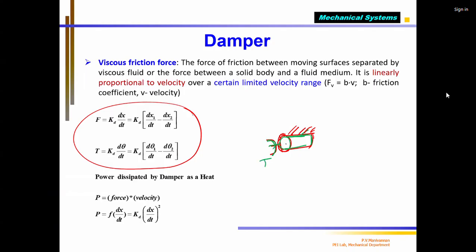So initially it was like this. Before rotation, theta was 0 degrees. Now I am giving a torque, so the angle increases. Theta increases 1 degree, 2 degrees, like this. Right? That's what we are talking about. The angular displacement d by dt means angular velocity, the rate at which the inner cylinder is rotating with respect to the outer cylinder. That depends upon the damping torque.